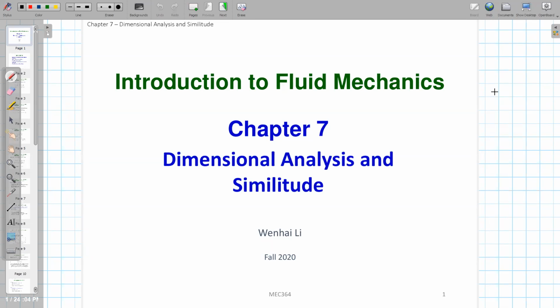And at the end of chapter 6, we're also talking about the irrotational flow, okay. So if you have inviscid, incompressible, plus the irrotational flow, all these 3 conditions, and if the flow is steady, then we also know that the Bernoulli equation can be used inside the flow field for any 2 points. So if the flow is irrotational, in addition to inviscid incompressible flow, you do not need to use the Bernoulli equation along the streamline. You can use it everywhere, right?